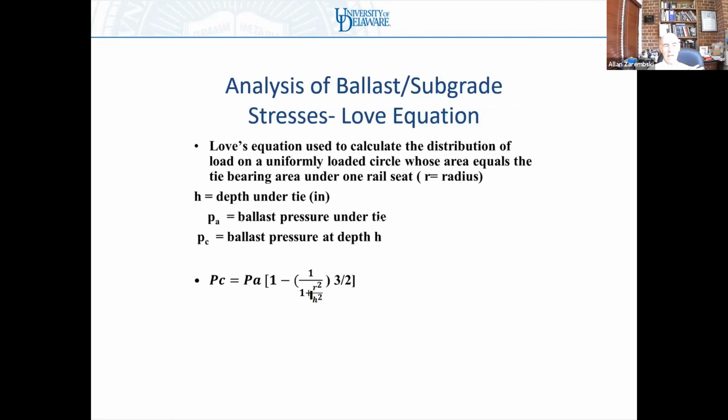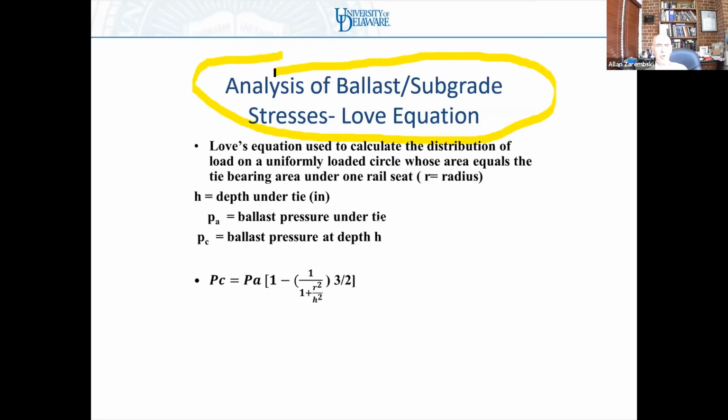Now, as I said, both these models are fairly simplistic. And there are some other models that I just want to introduce you to. But we're not going to be requiring you to use this in this class or in my exam, but I want you to be exposed to it. The next level up of sophistication is what's called the Love equation, which is used to calculate the distribution of load on a uniformly loaded circle.